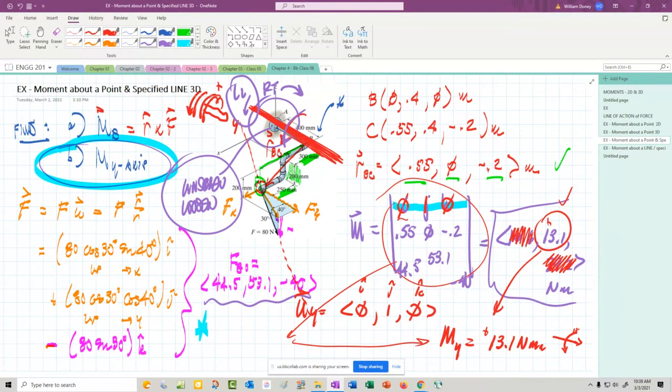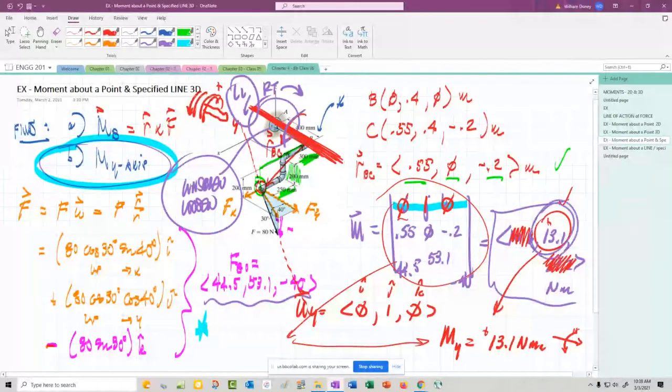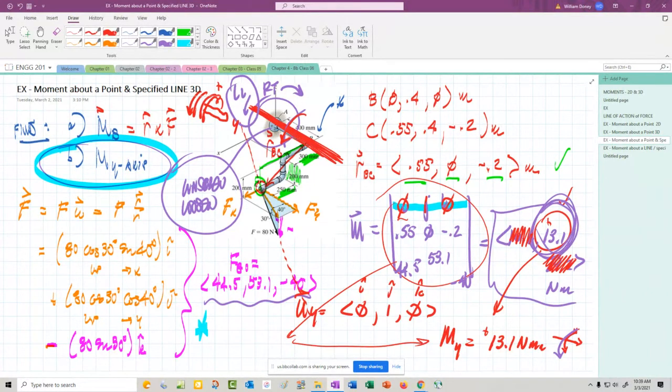Right, with a screwdriver, right? You turn it to the right, clockwise, it tightens. Left, it loosens. So since this has a positive moment, meaning it's going this way in a positive direction from the right-hand rule, this would have a tendency to try to loosen that pipe connection up.